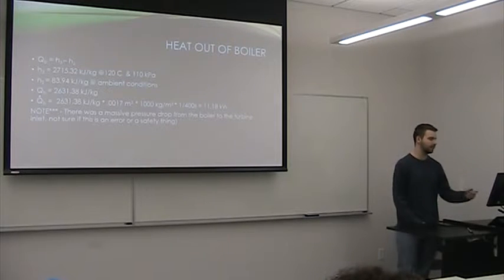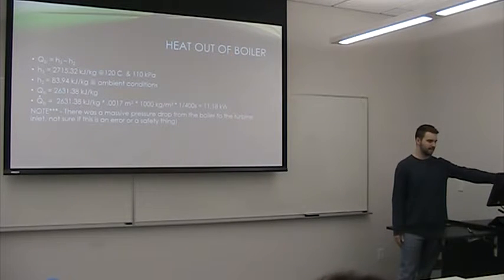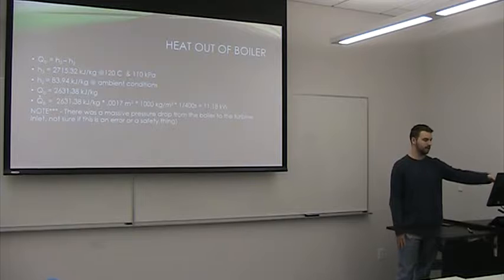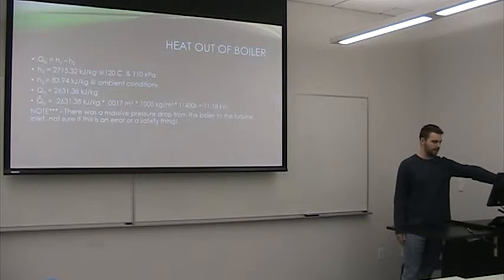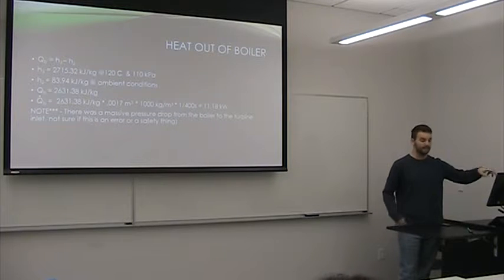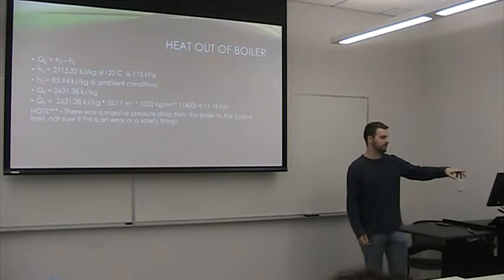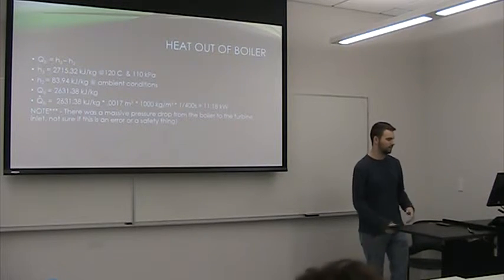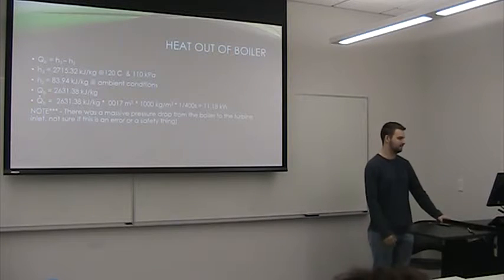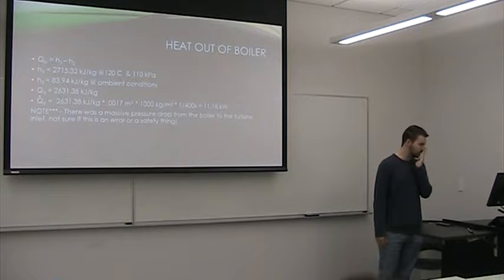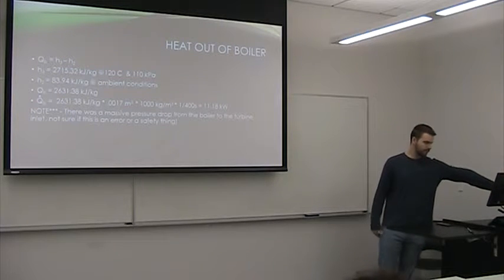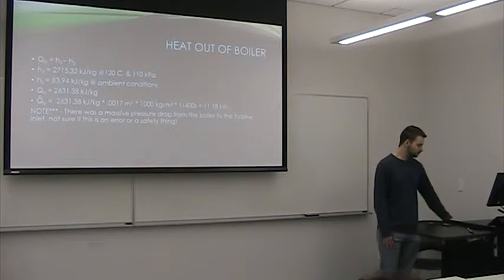But here are the calculations that I used. I used the inlet and outlet conditions of the boiler, and the inlet conditions of the turbine for the outlet of the boiler, just to make things line up right. And then there's the mass flow calculation with the heat flow.